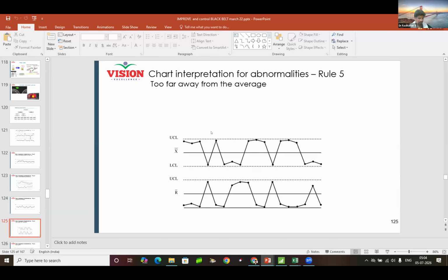Here you can see data are far away from the center line. So that is also a possibility. What about measurement system issues? The measurement instruments may have poor resolution or round-off values. Let us say, for example, a vernier caliper can measure only to the nearest 1 mm. When finer measurements are needed, they will round everything to 1 mm.